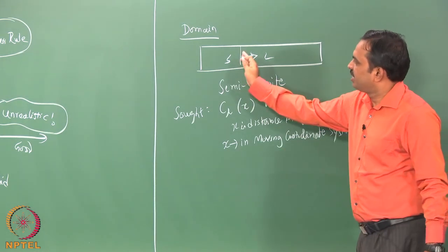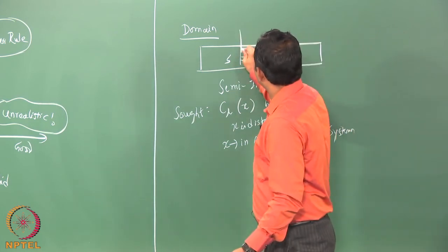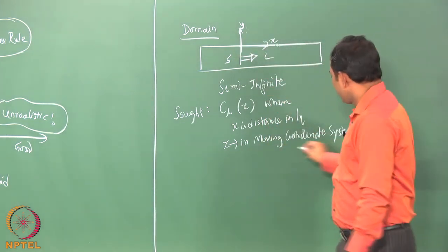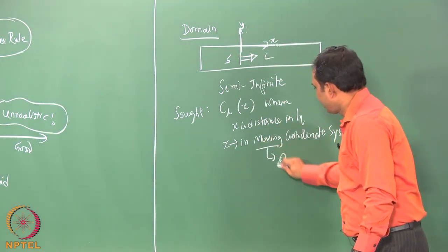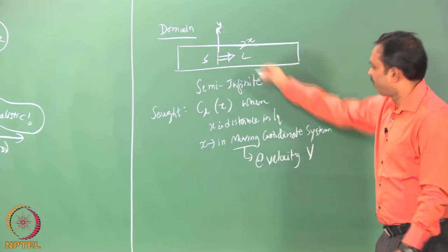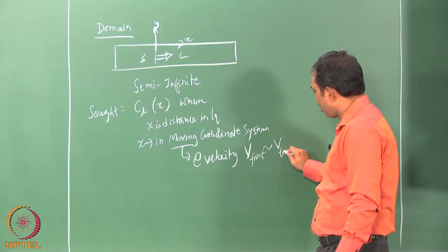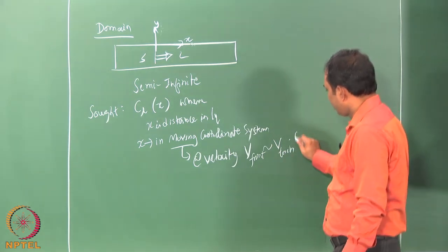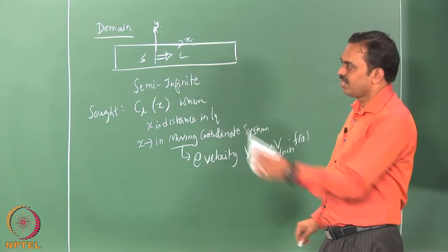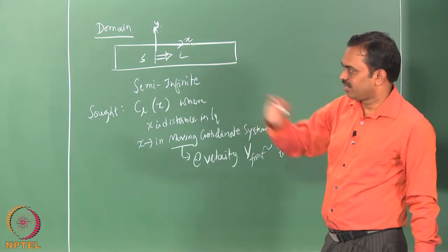And at what velocity is this interface moving, or the coordinate system that we have fixed? It is moving at a velocity given by the velocity of the front, and that is related to the velocity of the torch through a trigonometric function, which we can apply for the angle that it is growing with respect to the vertical. The vertical is the direction of the heat source, and at an angle the solidification is happening.